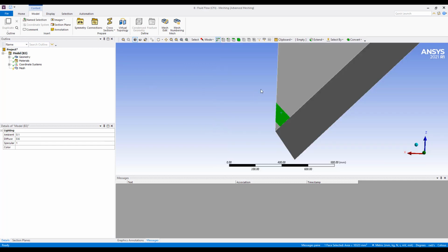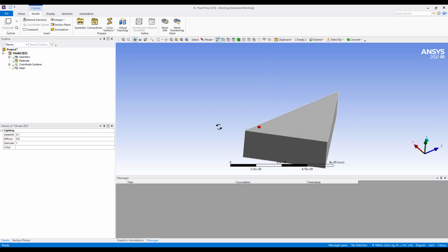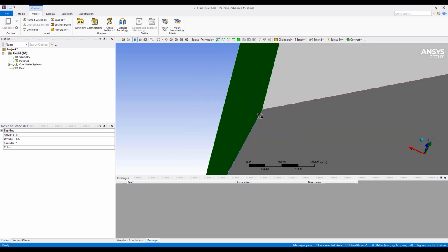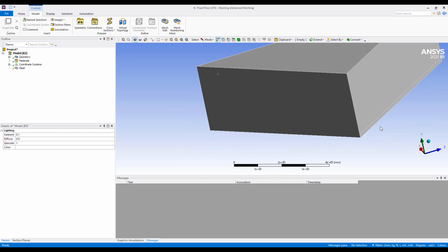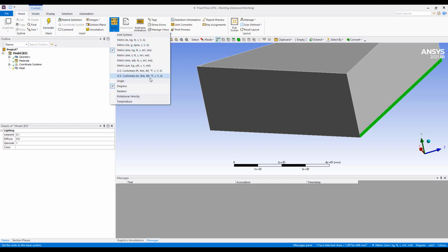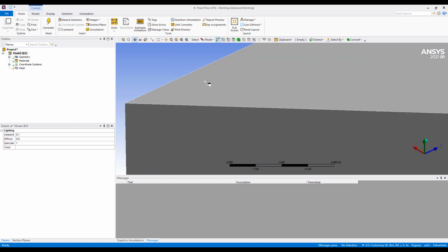Okay, so this is our simulation of the diffuser. It's a 1/8 sector of a standard ASHRAE room. We're modeling a square diffuser here, so this will be our diffuser. These are the symmetry planes, and then I have an outlet specified on the bottom here. And the goal is to try to figure out the performance of the diffuser as a function of the throw distance, so we can come up with a good model for it. So let's go ahead and set up this simulation here.